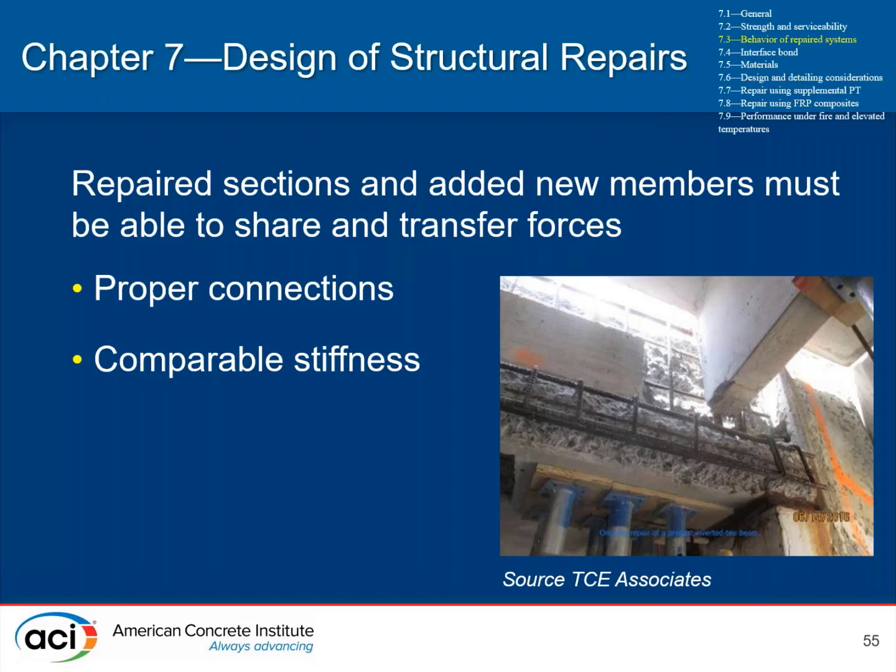But also in other repairs, anytime you're repairing concrete with these types of methods, you're relying on, again, as I mentioned before, the bond and the shear transfer and compatibility through those materials. And if the stiffnesses are vastly different between the sections that you are repairing or supplementing compared to the existing structure, load is going to be redistributed. So making sure that those connections and stiffnesses are evaluated and considered, such that you're sharing the load as it's intended.